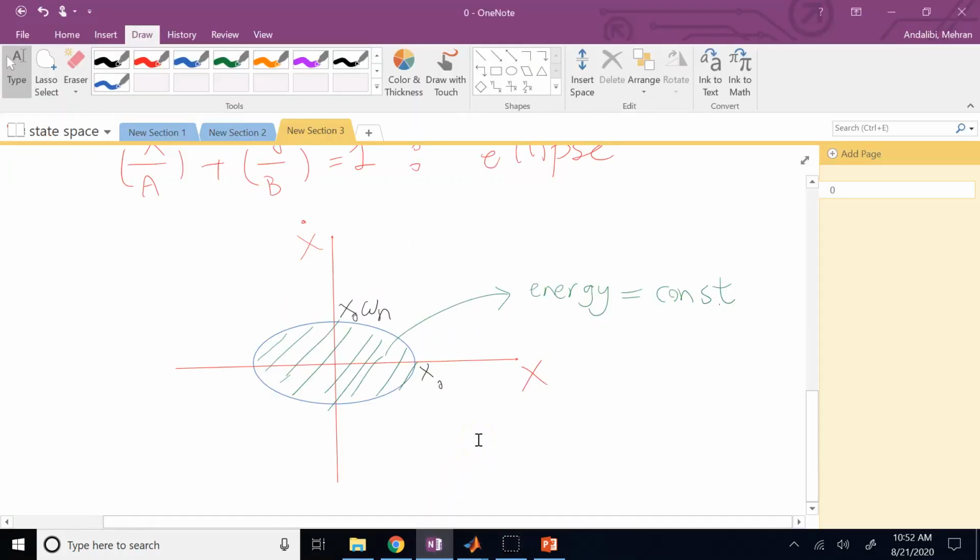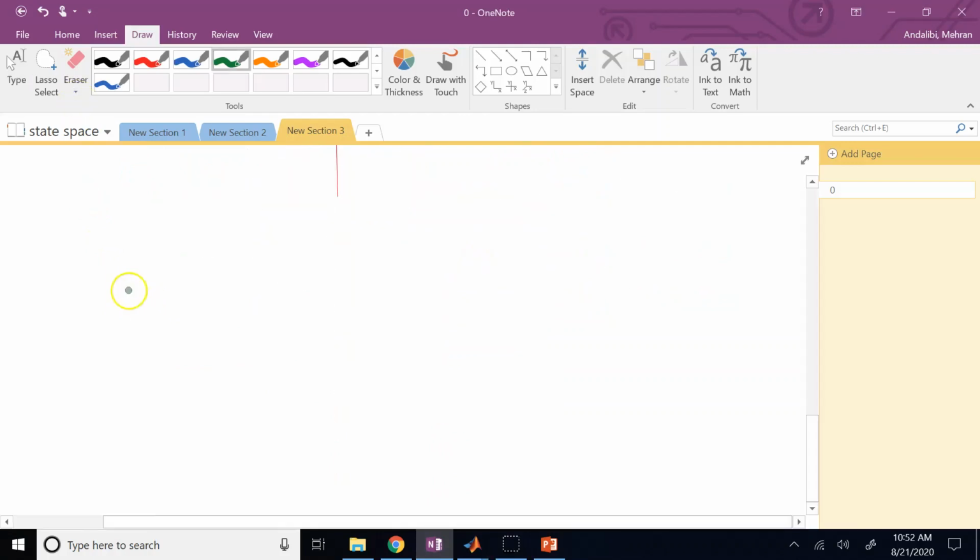So this time your equation will have one more term in it. This time you have m x double dot plus c x dot plus k x equals 0. Therefore, your x double dot, as I said in Simulink, you have to calculate the highest order derivative based on everything else. So it is going to be negative k over m x and negative c over m x dot.